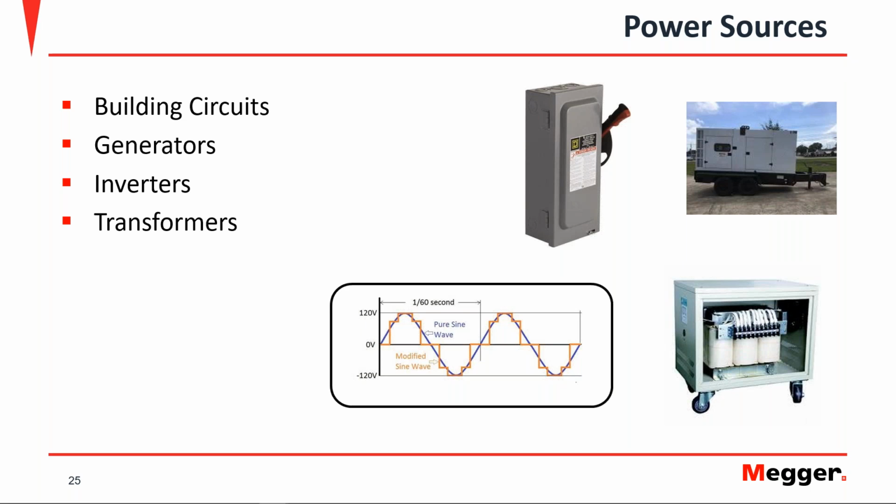Remember, most of these instruments step the current up, so you have a transformer inside. If you're feeding it with bad quality power, you will get something really similar in the output, and of course that can affect your results. So make sure the power source you're going to use is properly sized, and in terms of power quality, that it won't affect your test results.